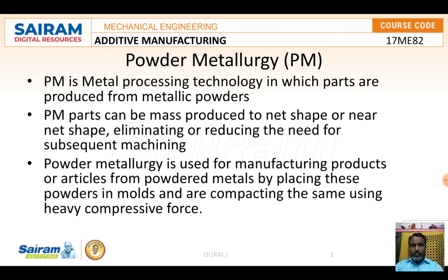In this process, the production of powder metallurgy parts involves mixing elemental or alloy powders with additives and lubricants, compacting the mixture in a suitable die, and heating the resulting green compacts in a controlled atmosphere furnace to bond the particles metallurgically. Nowadays gears and other things are manufactured with the help of this powder metallurgy method.